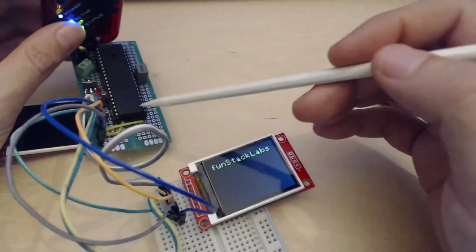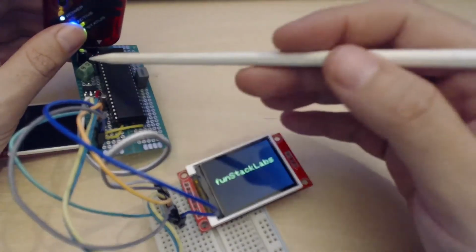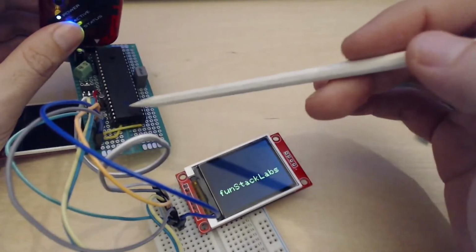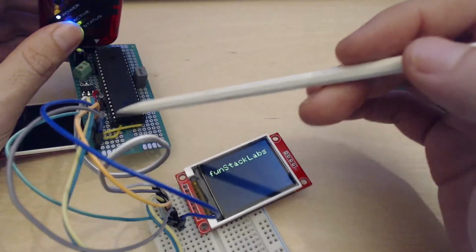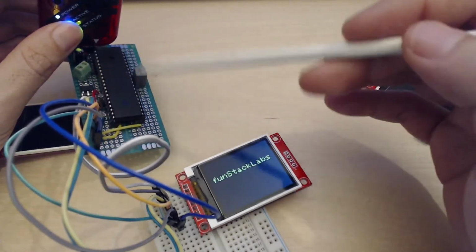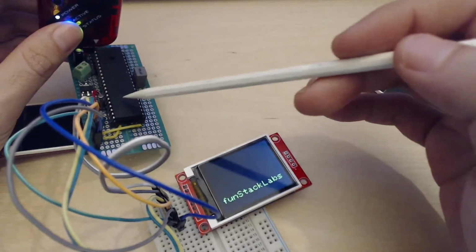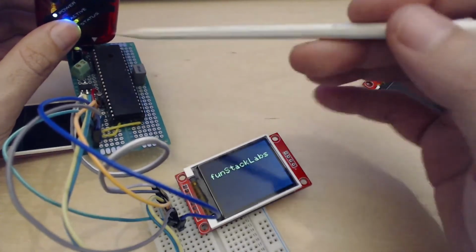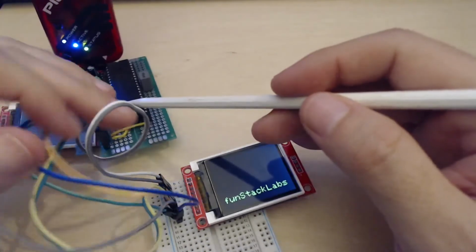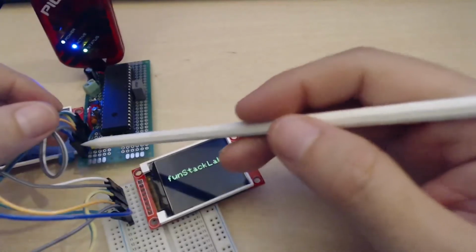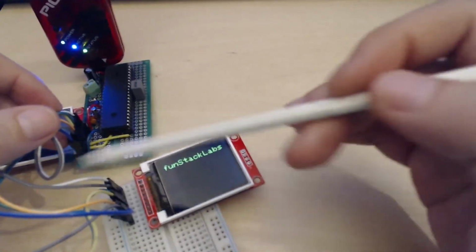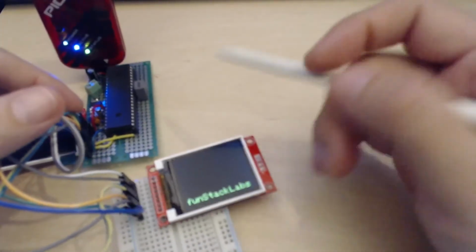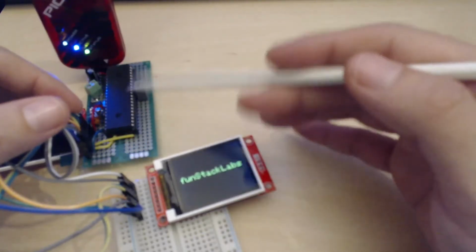So yeah, we have this microcontroller. We have some bypass caps for the power, the voltage regulator, and a bit of crystal stuff going on here, just because I wanted a real-time clock in this one. Not that the processor needs any external oscillator, because it has a high frequency internal oscillator with PLL, it can go like 64 megahertz without any external crystals. All the others are just connections really. There are just some pin headers here, and just jumper wires coming to the breadboard, and everything is connected to the pins on the graphic display. No resistors, nothing at all, straight connected to the microcontroller.